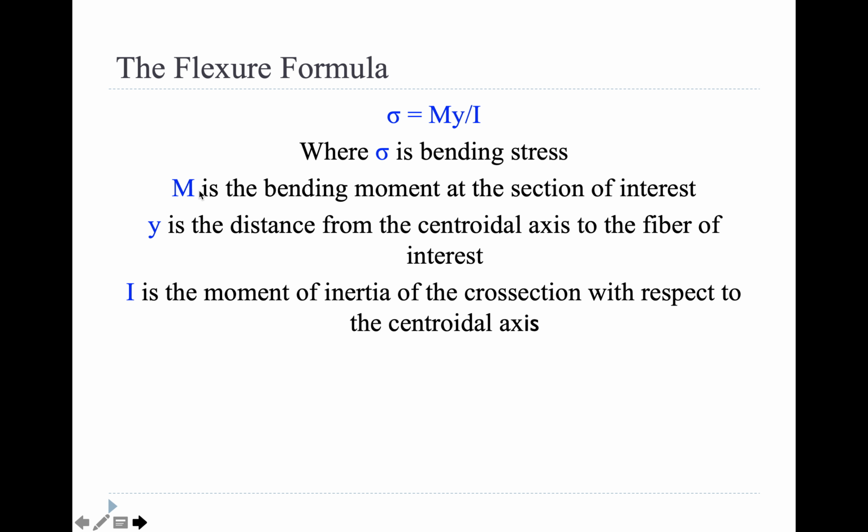Okay, so if it goes up to positive 15, but it goes down to negative 35, well, the beam doesn't care whether it's tension or compression. That's just the maximum force it's going to feel. So you need to design to that maximum force that it's going to feel regardless of compression or tension or positive or negative moment. It doesn't care.